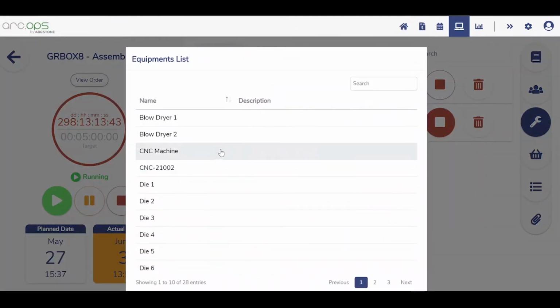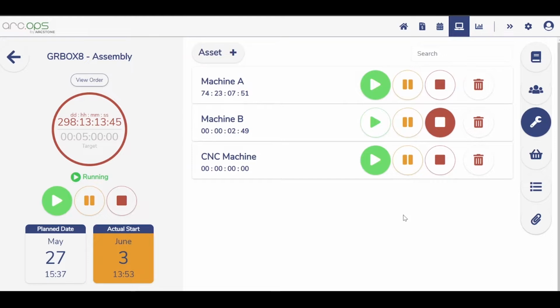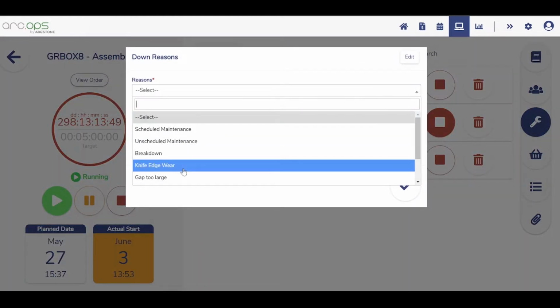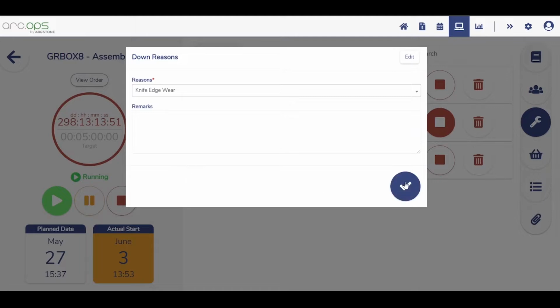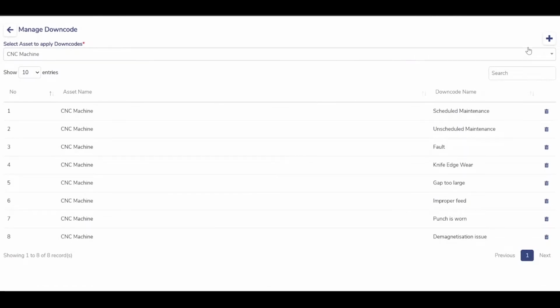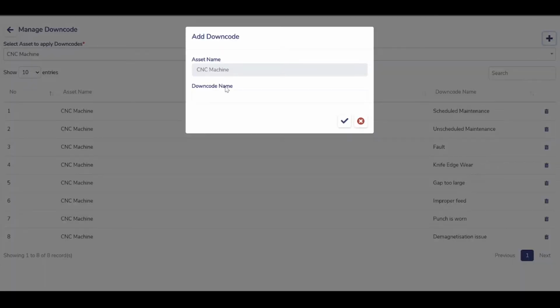What you're seeing first is our way to manually capture the data, where I can select specific machines that are in use and the current state that they are in. I can also specify specific reasons why a machine might not be available. So this will later let me drill down into my OEE and find out specific reasons why my OEE might be affected and where I can optimize the efficiency.